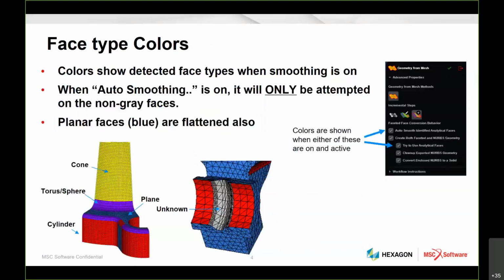Another important thing is planar faces. Faceting is not as important with planar faces, but they're not always planar. These faces meet slightly off. And if I use these faces later on to do splitting, like if I want to split this piece on this plane back here, and it's not very planar, it can cause some poor splits or have a split fail. So when you have the blue, it actually makes them more planar and flatter too.